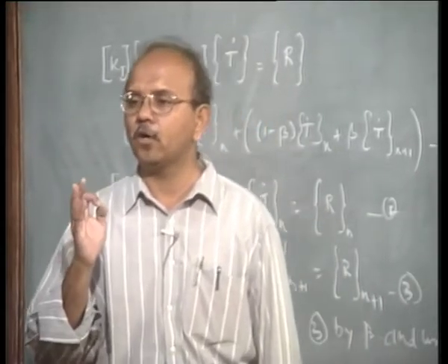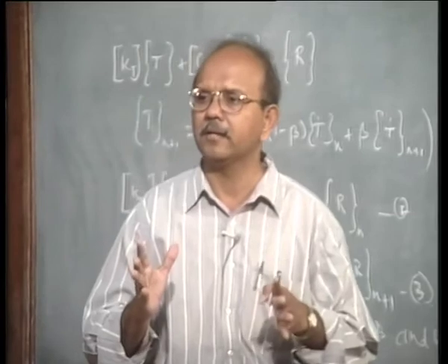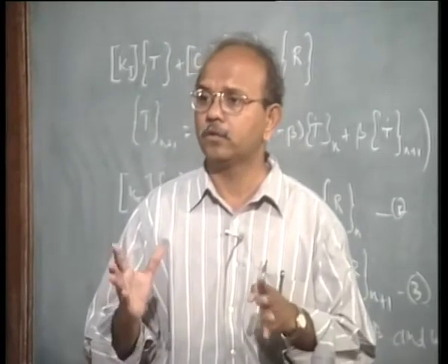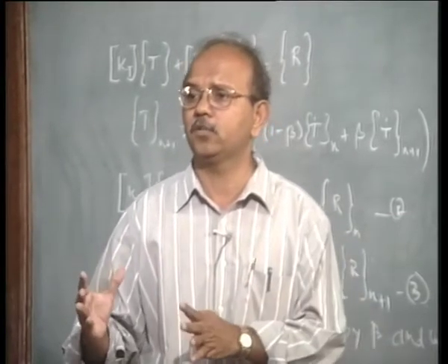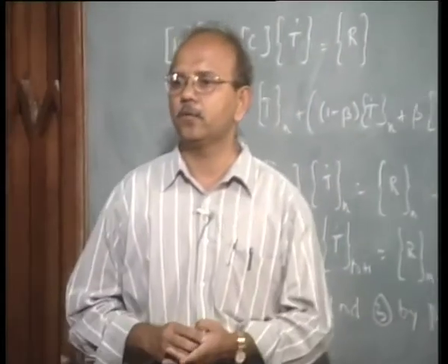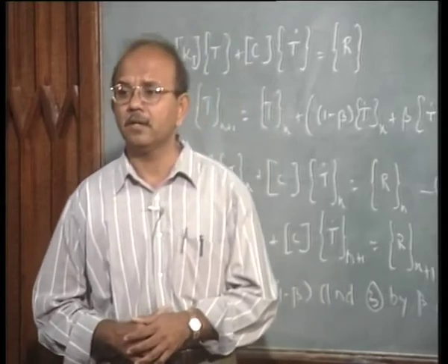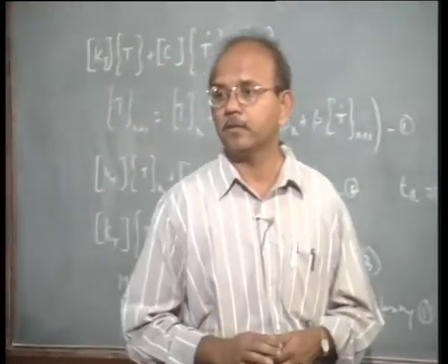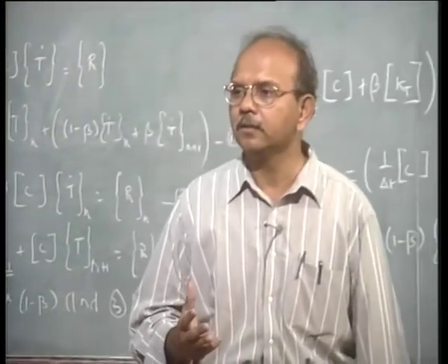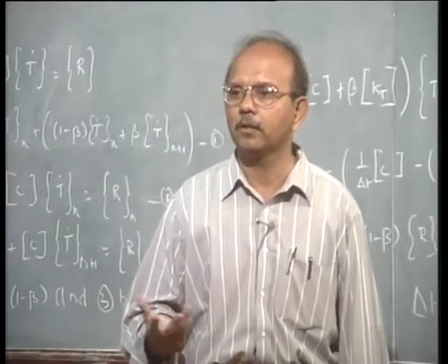So, whenever we talk about error, we talk about combined error, between both the finite element error and the assumptions that you have made to simulate the process. On the whole, about 15% to 20%, personally I feel we will be very happy, and that is the type of results we have been getting when compared to the actual graph.